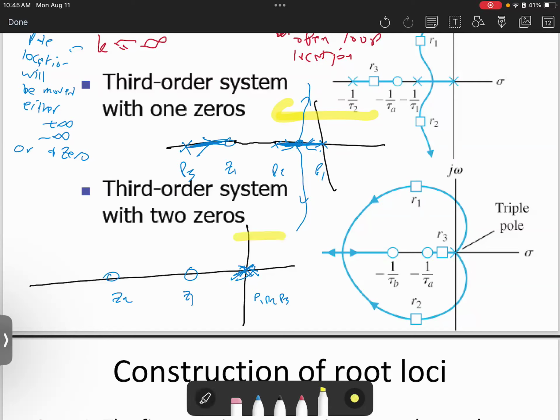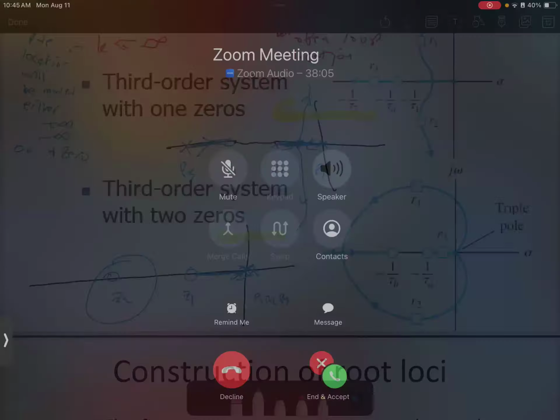Start counting from right to left. How many poles and zeros do we have? From left to right, 3. Therefore, this is counted within the region. Then after that, P1, P2, P3, and Z1, this is 4 poles and zeros. Therefore, the region between Z1 and Z2 is not counted. Then after that, there is a Z2. After Z2, the total number will be 5.